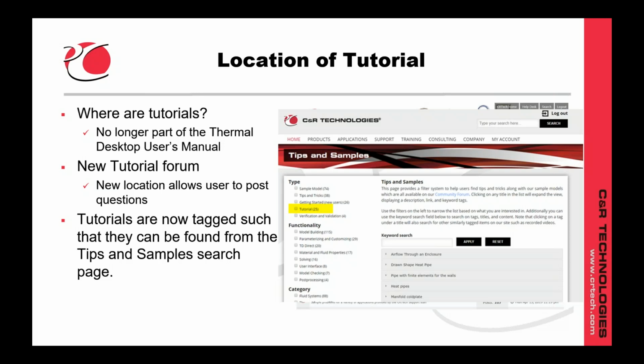Another one is, where are there samples or tutorials for FK locators and tees? So as part of the 6.1 release, we went through and tried to update the majority of the sample problems that we have on our website. Most, if not all, of those have been reworked, and many of them now include FK locators, since we found them to be so much more convenient than the old methods where the FK is hidden underneath each path. Especially any samples where we had inlets and outlets where you might want to apply constrictions to catch choking, those have all been updated.